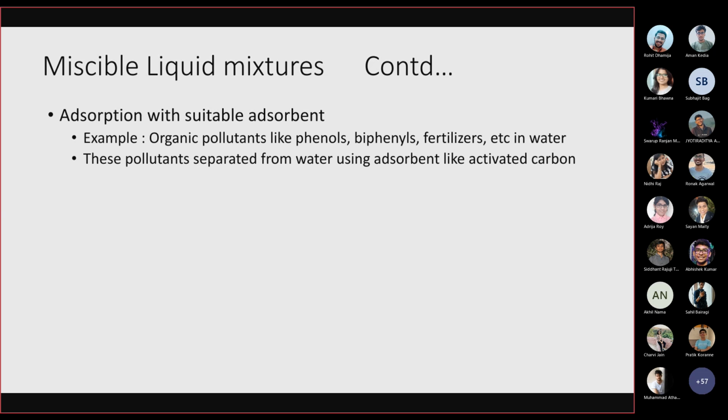Another scenario, in the case of miscible liquid mixtures, another unit operation we can use is adsorption with a suitable adsorbent. Here I'm giving an example. Suppose we have water with some organic pollutants like phenols, biphenyls, or dissolved fertilizers present in it.